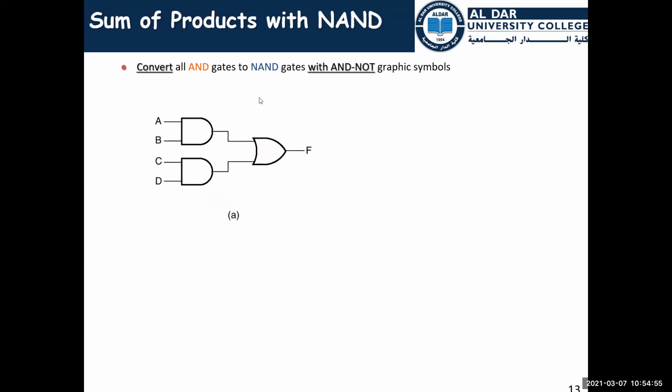I have this circuit and I want to convert it to all NAND gates, as you see at the top, the title. We begin with this circuit because we have our logic. I get the logic from the client, and the client asks me to do some specific control. I do the truth table and Karnaugh map, then I get the Boolean expression, then I draw my sketch. This is the sketch of my circuit. I want to convert this from AND and OR gates to NAND gates only.